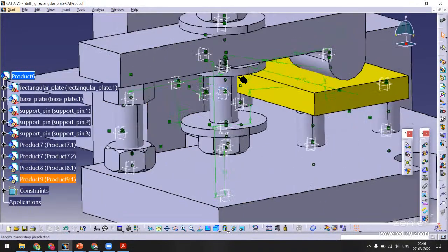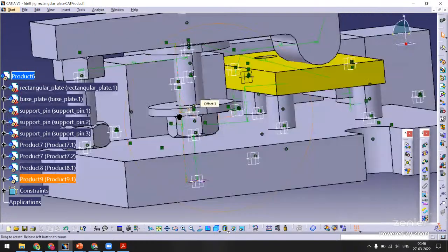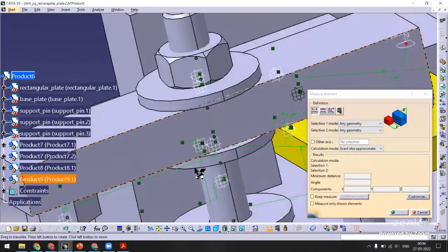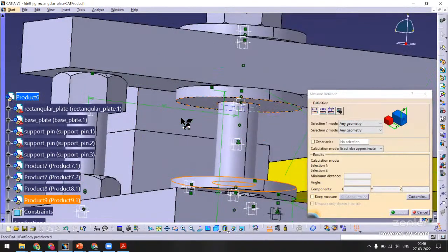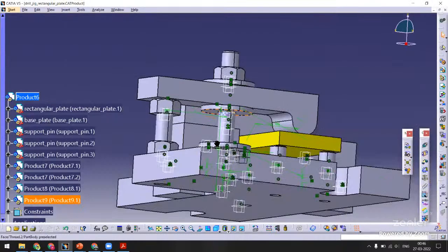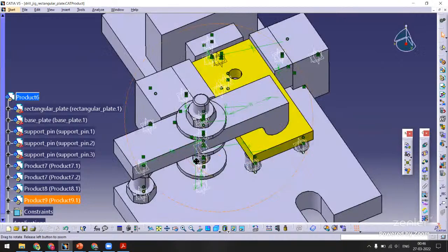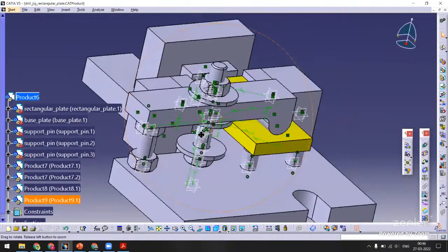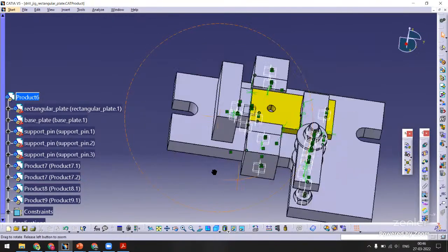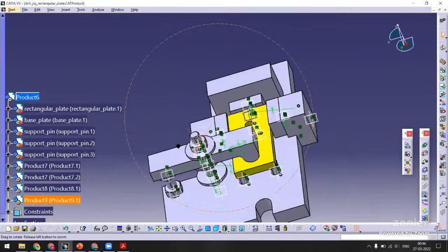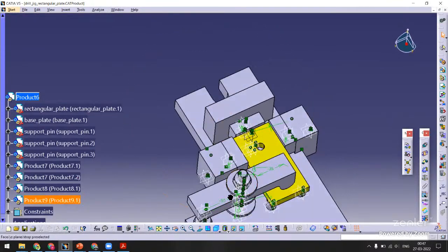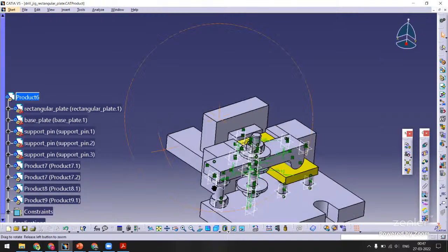So now what we need to do is, we need to apply a spring here. Let us measure what is the gap. The gap is 23.4 mm. Okay, more or less, we have done everything. Is there anything left? I have put the clamp. So the location is done. The clamping is done, but for the spring, we have the base plate.